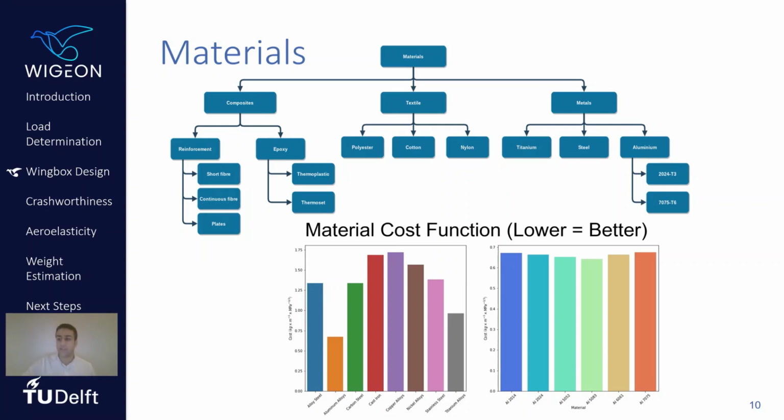That is why the best material selected for this purpose was 7075-T6 for most structural components due to its corrosion resistance and high tensile strength, and 2024-T3 was selected for the skin due to its corrosion resistance and the fact that the tensile strength is of tertiary importance for the skin.